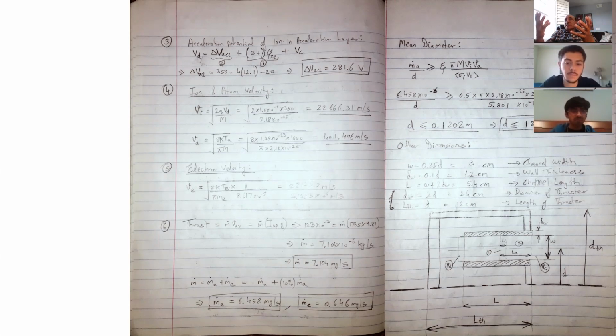I guess this must be the ionization reaction rate. So you ionize it to that level. That needs a little bit of understanding. But basically, the idea is that you have to ionize it so you get the diameter to contain that gas and maintain it in this ionized form. And then you have interdependent relationships with that diameter to size the Hall thruster, right? So yeah, that's the entire crux of the dimensioning of the Hall thruster.